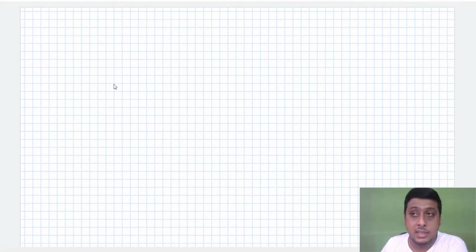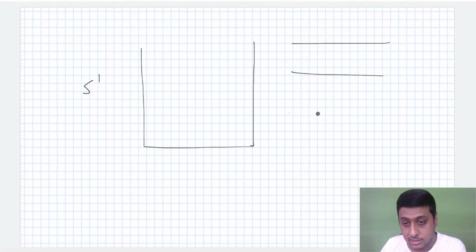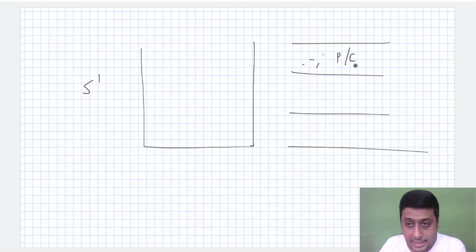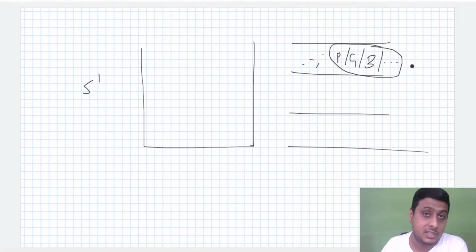Filled up soil means there may be certain soil which was filled on the site to level the land. For example, let me draw an excavation pit. For example, this is the excavation. What exactly is happening? 5 feet. If I take the cross section, this is already excavated. If I take the layer of the soil, for example like this, we might get some very loose soil with plastic, glass, or brick bats and many other particles inside this soil. So these soils are the filled up soil, which we come to know by seeing these additional products or foreign materials present in the soil.